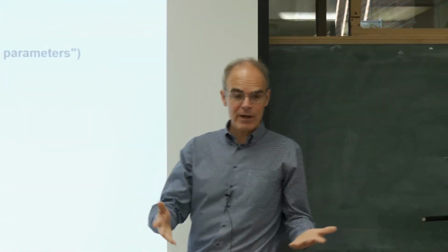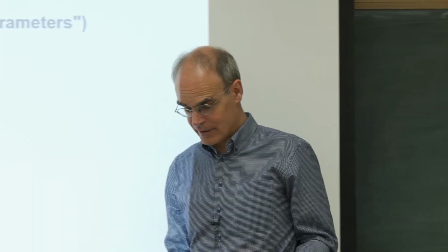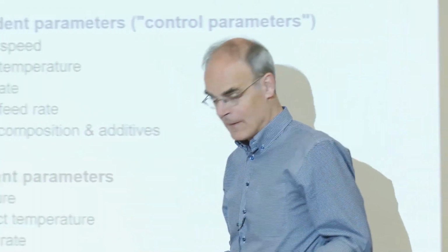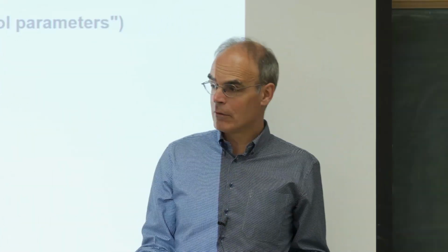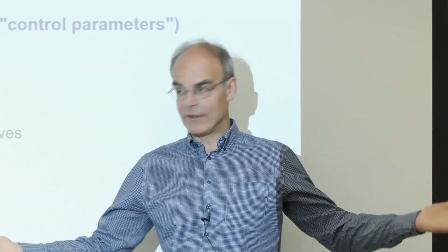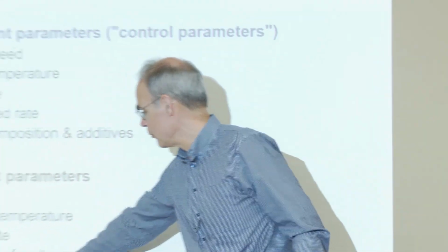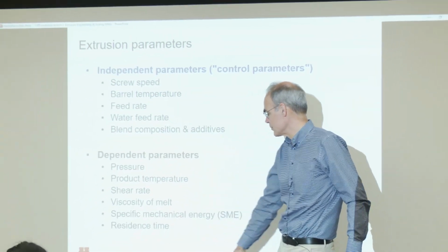And the reason I mentioned that blowing up of the single screw extruder in Germany, with that trial with 11 tons of flour, there was a viscosity issue. If you have a way lower water content than you're planning to, the viscosity is way too high. So viscosity of the melt you can control over the water content and temperature.